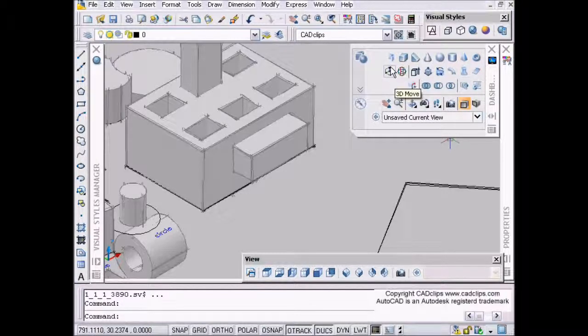Talking about AutoCAD 2007 3D, and very much like the 3D rotate, we're talking about the 3D move command on my dashboard. The 3D move command is very similar, where we can constrain our movement. We've had this type of command in the past, but it didn't work as nicely, and again it is another great tool in our arsenal for creating 3D objects, an improvement in AutoCAD 2007.